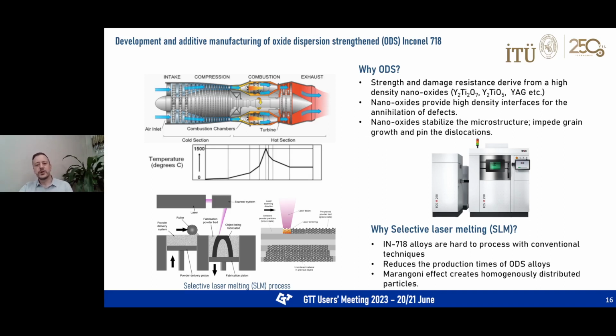So, why has the research group decided to use nano-oxides? There are some successive studies in the literature showing that oxide dispersion strengthened ODS alloys exhibit outstanding stability at much higher temperatures due to the existence of nano-oxide particles, which are reported to be mostly yttria titanium oxide or yttria aluminum oxide or hafnium titanium oxide systems.